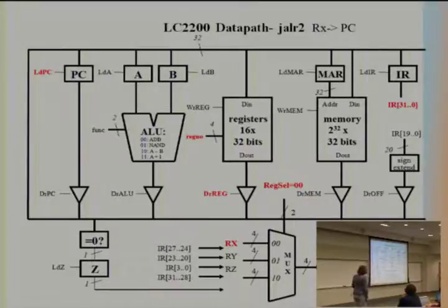Exactly. So one more time, we know what is in register RX. Now I just have to select that I want to read what is in RX. And those 4 bits, which are the address for RX, will be activated here. We'll let it write on the bus by setting the RX to 1. And then we load that to PC. It wasn't that bad, right? Yes.